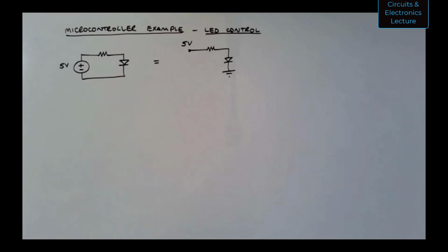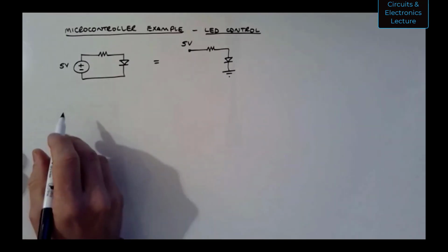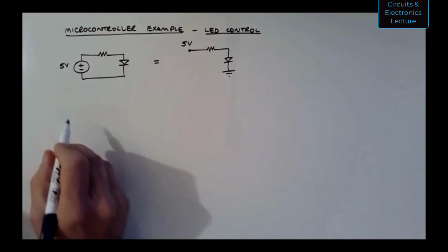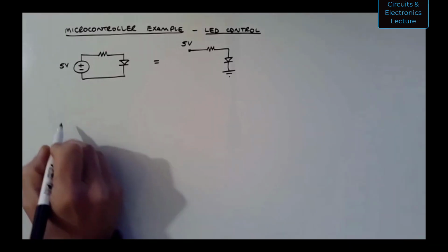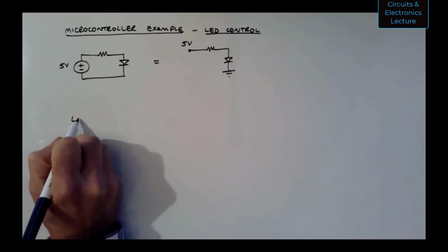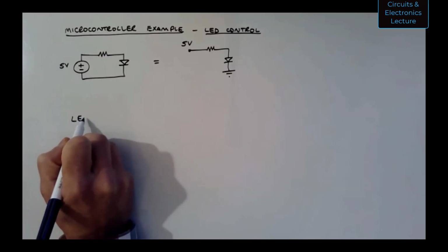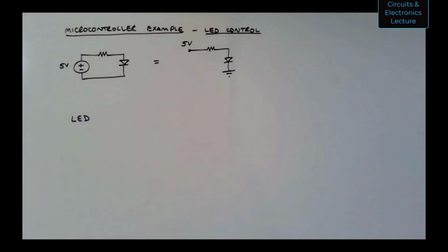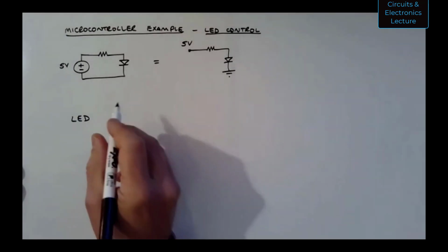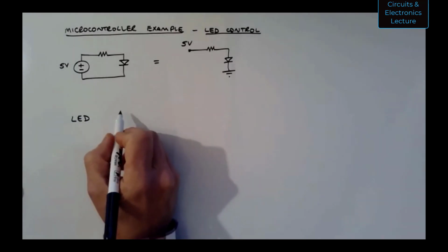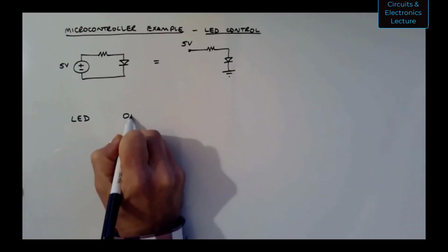That LED would light up, the resistor limiting the current. So let's talk about how to light an LED with a logical value. What I mean by that is, if you have 5 volts or 0 volts node voltage on one side or the other of an LED, how do you get it to light? Let me show you what I mean.